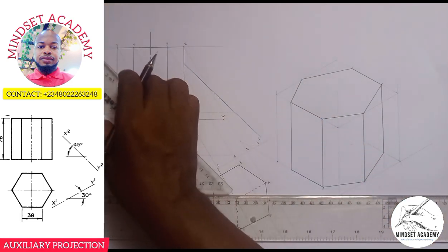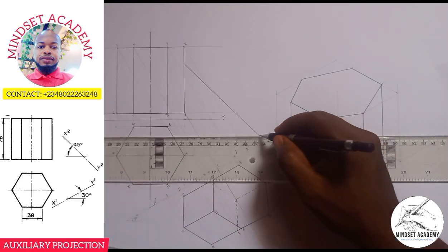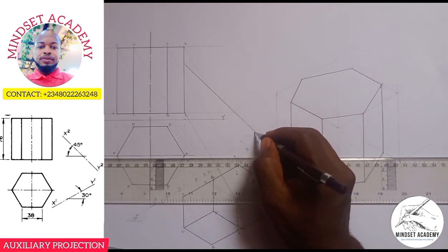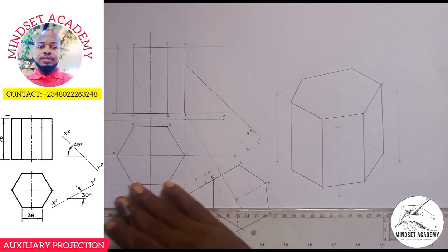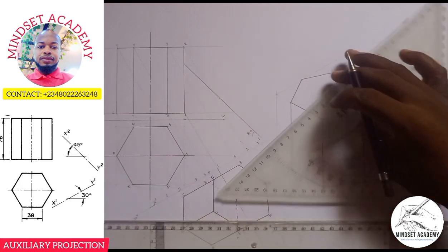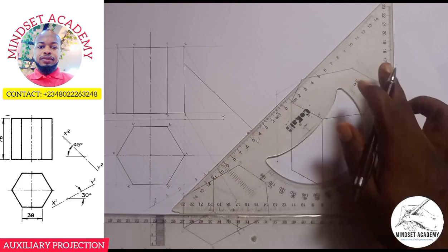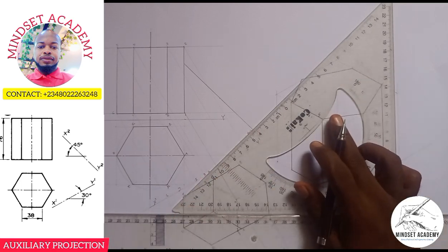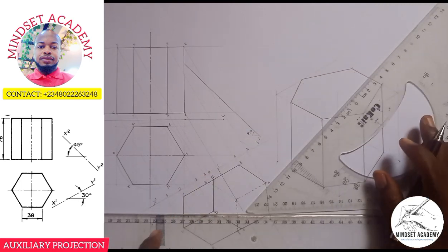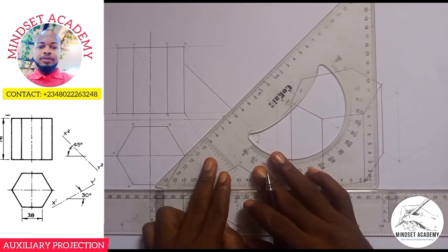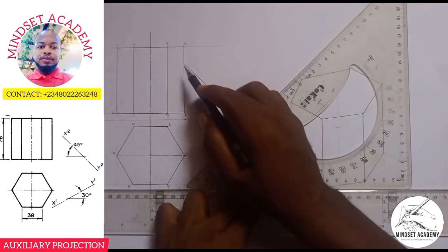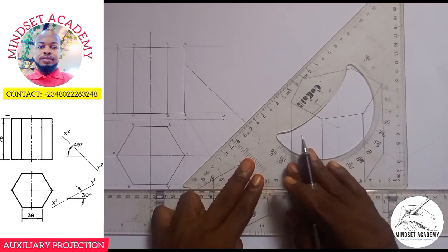Right? So the angle here you see is an angle of what? 45 degrees. You're going to project all this part outward. Since it's 45, you must use 45 to project because that will make it 90. Because this was 30, I used 60 to project. Please don't forget that, because the angle of projection and our reference line must always be 90 degrees.